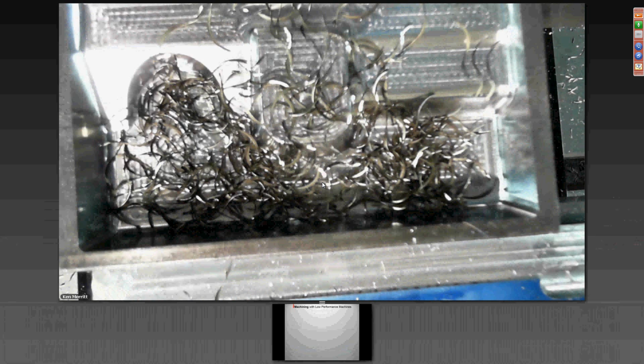It's not going in and out of corners, and it's not changing directions, where because it's changing direction, the angle suddenly rises up and creates more linear load on the tool. It's keeping a very, very consistent chip thickness. So all of those stresses and forces on the tool are staying very, very stable, so that carbide is going to last a whole lot longer. Okay? I hope that kind of makes sense for you.